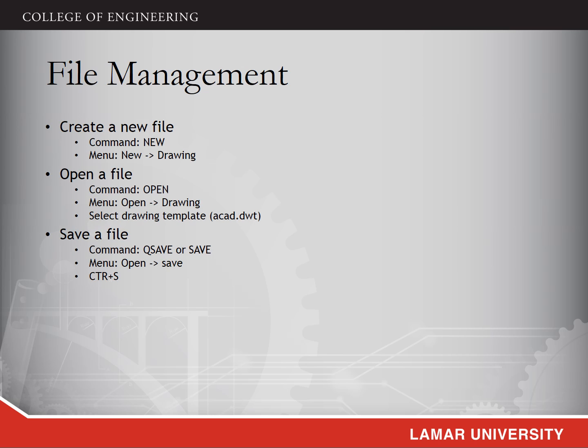To save the file, you have three methods. You can type the command qsave or save in the command window, or go to the menu bar, choose open and save, or you can use Ctrl+S to save one file.